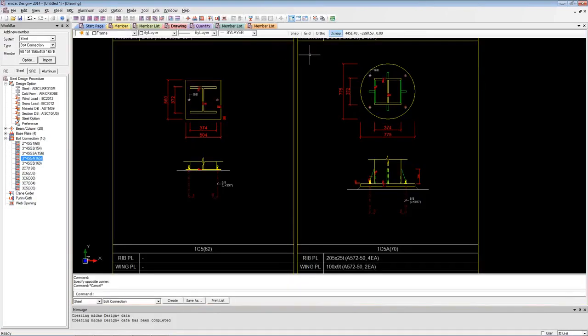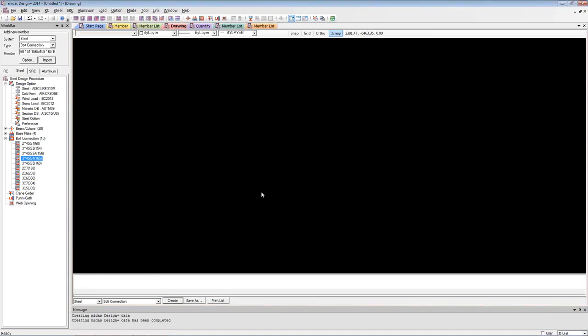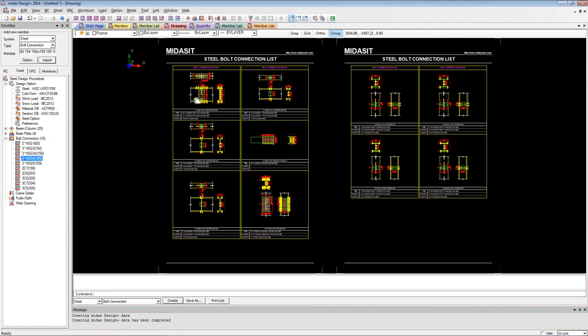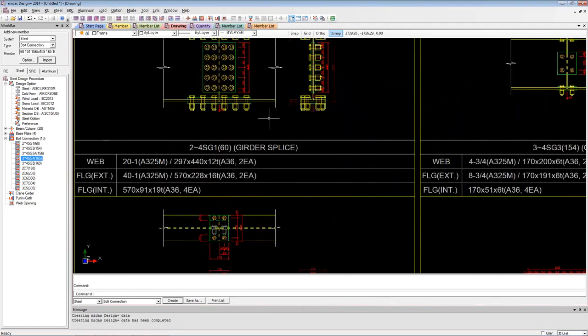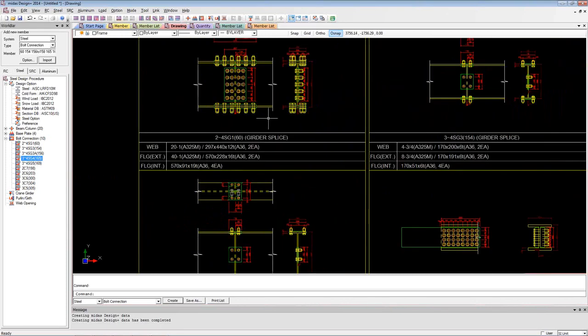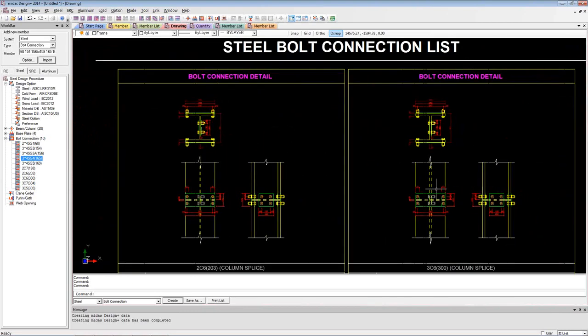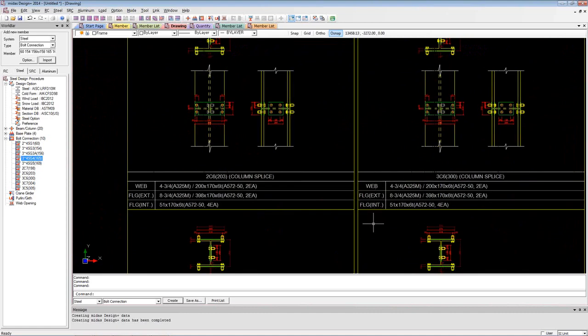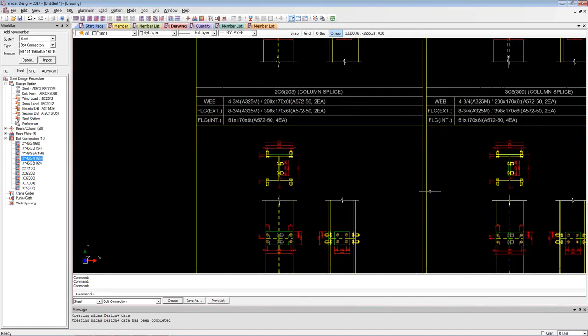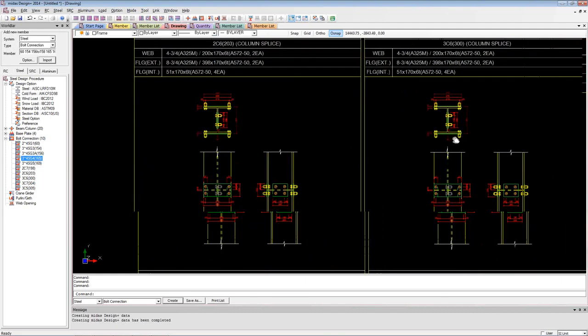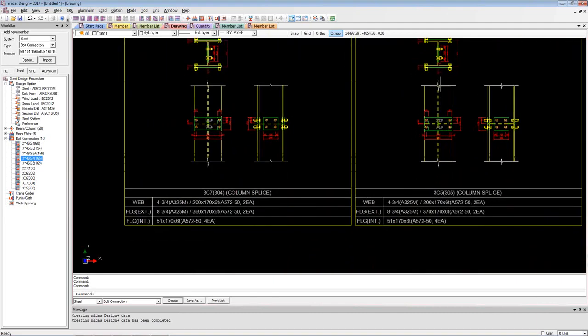And again, you can get the design section also. So I'll just click on create. And you can either scroll in, or as I've shown you before, since it is compatible with AutoCAD, every command of AutoCAD, you can type in zoom and zoom in. You can create lines or insert text. That's all up to you. So it will be there on your screen in just a few seconds.